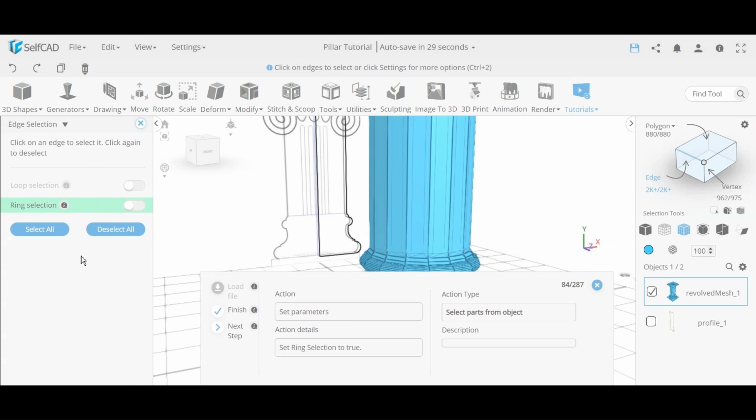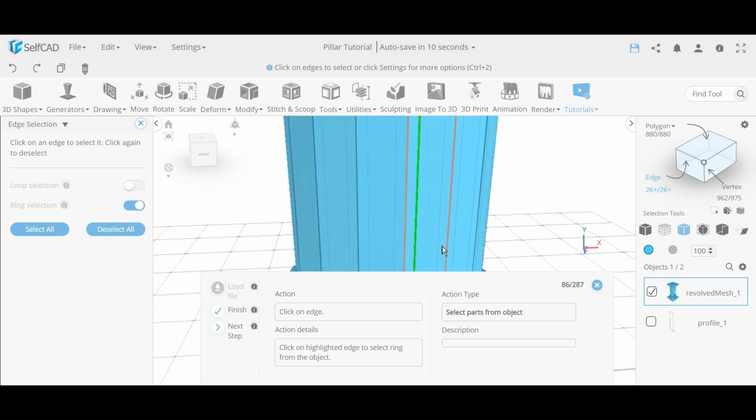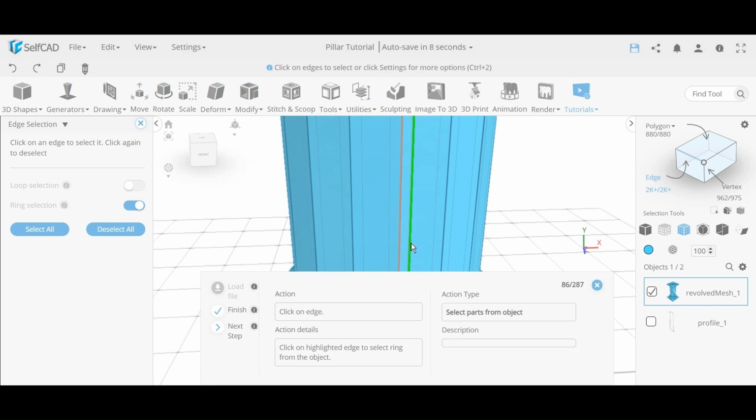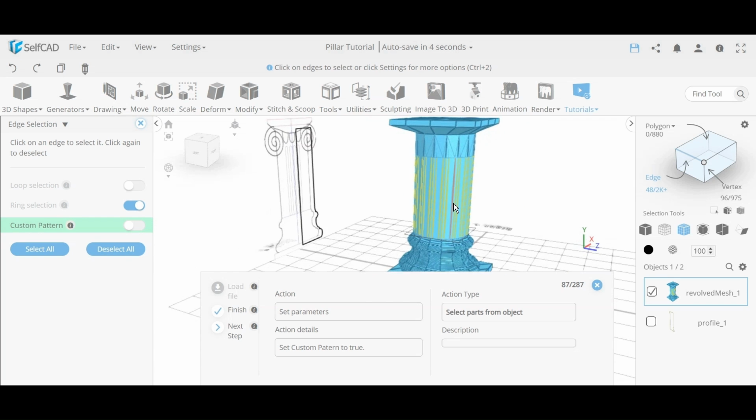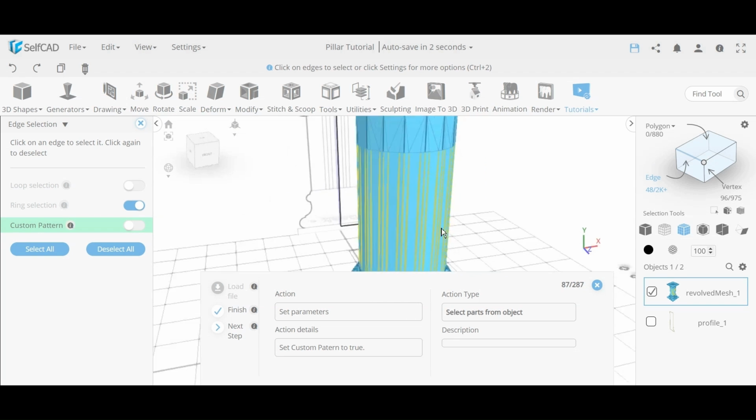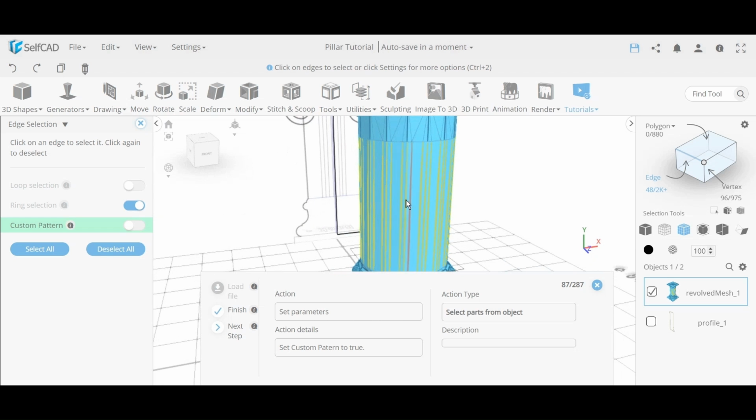And in the advanced setting, we're going to use the ring, same thing to select them. So a loop is one that closes a loop. A ring is consecutive. They don't close a loop. It's not connected. They're just in the same ring that makes it up. So now we go to ring finding, and you see we select this ring over here and click on the next one. Let me just select this. I take this, and okay, so we selected over here the entire ring. And look, it selected everything, all of these edges. But we want to select only part of it.